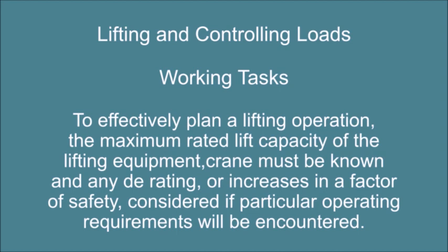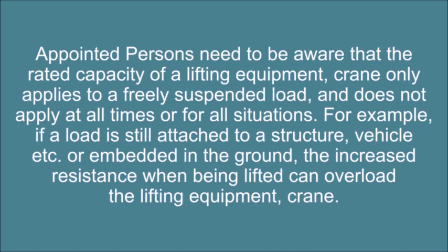Lifting and controlling loads. Working tasks. To effectively plan a lifting operation, the maximum rated lift capacity of the lifting equipment crane must be known, and any derating, or increases in a factor of safety, considered if particular operating requirements will be encountered. Appointed persons need to be aware that the rated capacity of a lifting equipment crane only applies to a freely suspended load, and does not apply at all times or for all situations. For example, if a load is still attached to a structure, vehicle, etc., or embedded in the ground, the increased resistance when being lifted can overload the lifting equipment crane.